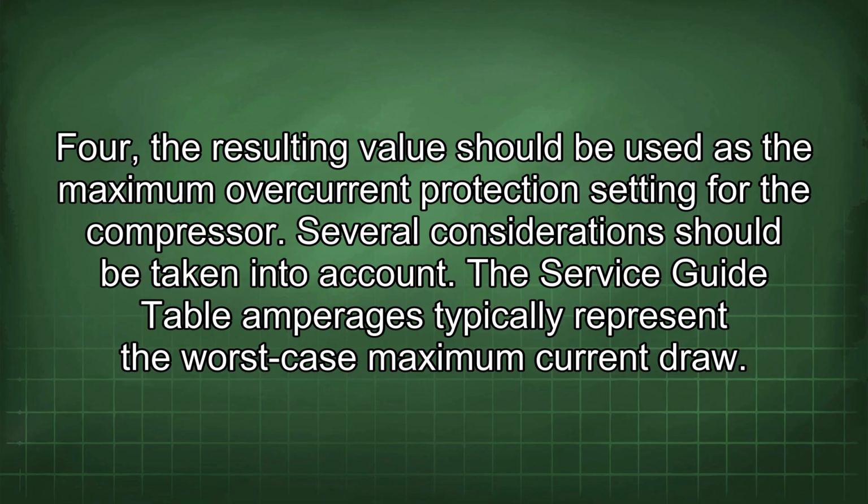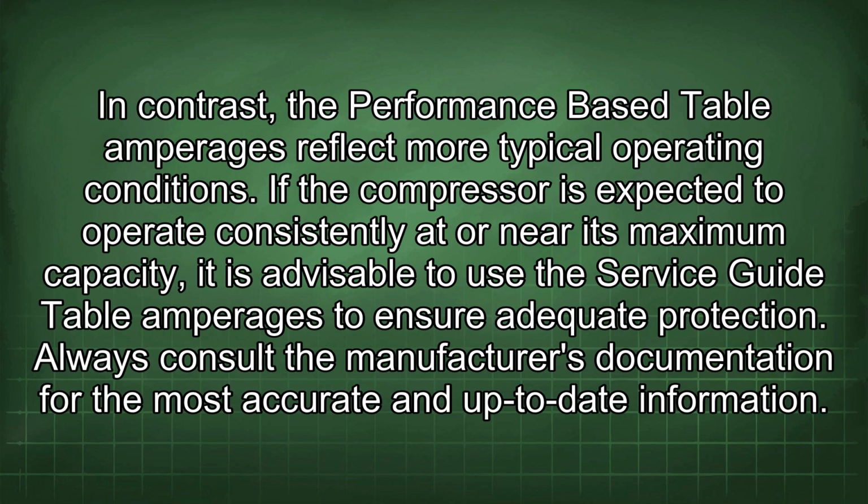Several considerations should be taken into account. The service guide table amperages typically represent the worst-case maximum current draw. In contrast, the performance-based table amperages reflect more typical operating conditions. If the compressor is expected to operate consistently at or near its maximum capacity, it is advisable to use the service guide table amperages to ensure adequate protection.